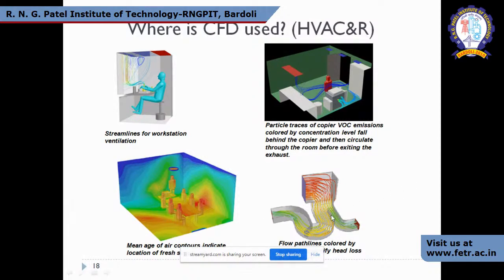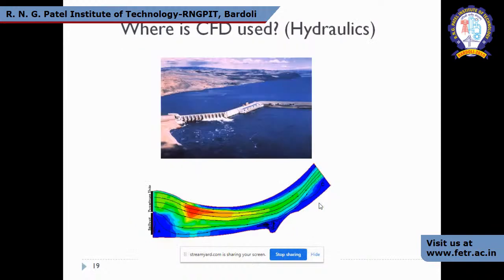Then there is simulation of the vent where we flow the conditioned air, as well as where the return ducts come. Even traditionally we have a traditional design for all these kinds of ducts. Hence, by using CFD, some popular approaches can be implemented and the duct design can be improved.